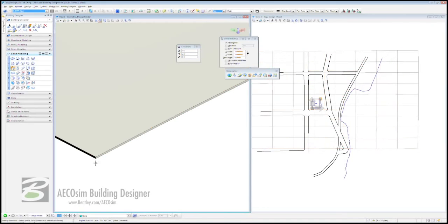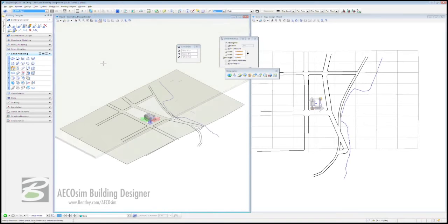And straight away, all I have to do now is click, and my site has been thickened to a depth of 2 feet across the whole site. And now, with all of this, we can come down to our next row down in our Solid Modeling tab, Draw on Solid. In the Draw on Solid dialog, you want to check the 4th icon in, Imprint Curves.